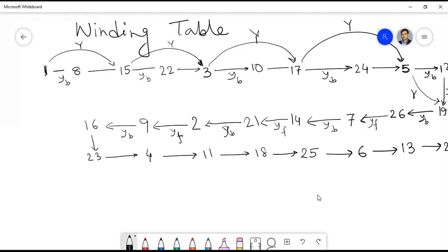Now, here you have seen that to start the design, the main important factors are the back pitch and also the commutator pitch. And the commutator pitch also determines whether the winding will be simplex or multiplex winding.